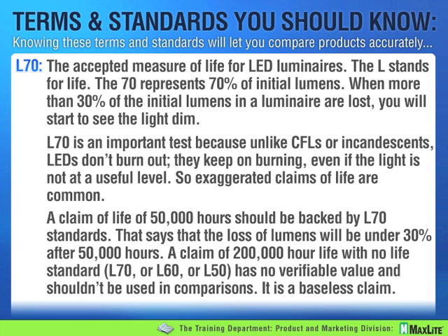because not only do they capture the failures, the outright bulbs that fail to work altogether, but it captures lumen depreciation. A brief translation is a 6,000 hour bulb in Japan is a 10,000 hour bulb in the United States. But for LEDs, all that goes out the window, because when everything is done properly, they actually don't fail to illuminate. You can take even some old LED technologies after 70, 80, 100,000 hours, bring them in a dark room with an eye loupe, and you could see a twinkle out of them, technically illuminated, but nothing useful coming out of it. So a new way to measure the life had to be developed, and the answer is L70.